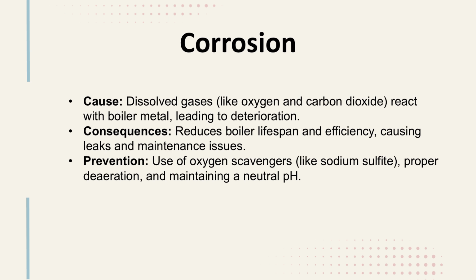Boiler corrosion is another serious issue that arises due to the presence of dissolved gases like oxygen and carbon dioxide in the feed water. These gases react with the metal surfaces of the boiler, leading to the deterioration of key components. Consequences of corrosion include reduced boiler lifespan, efficiency losses, and the need for frequent maintenance to repair leaks and other damage. To prevent corrosion, several methods are used.